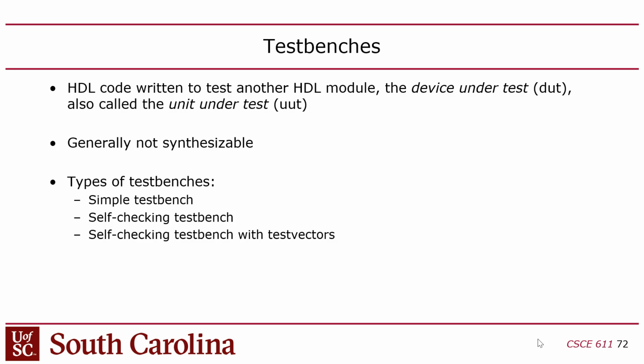Another big one is the delay operator. In Verilog, you can put hash sign 2 semicolon, and that will put a delay for 2 units of time. That's also not synthesizable. So if you have any non-synthesizable code and you try to synthesize it, you'll get an error because it's intended for simulation. But when you write a test bench, you're going to put a lot of non-synthesizable code in there because it's intended as a harness that's going to drive the inputs into your design under test, which is the thing that you're going to synthesize, and then it will check the outputs, and it will automatically check the correctness, and if they're incorrect, it will print an error. Does that make sense?